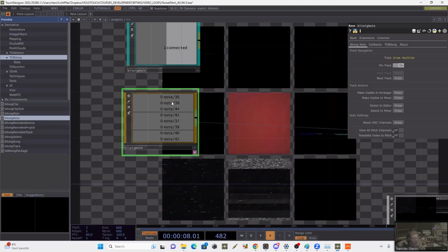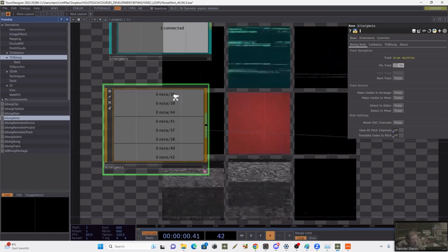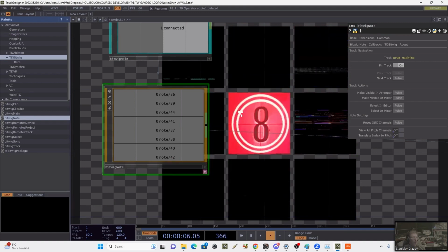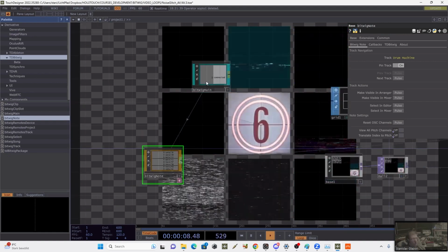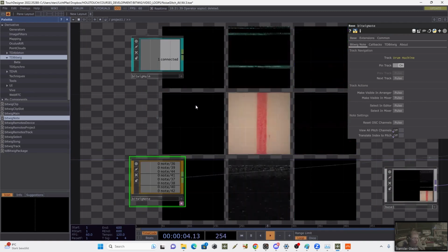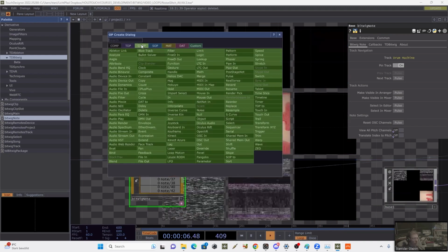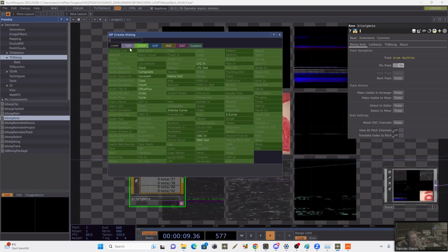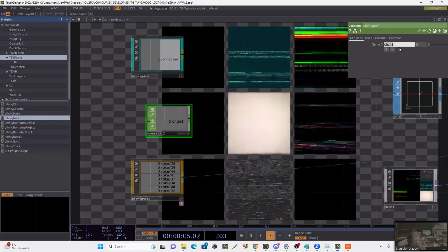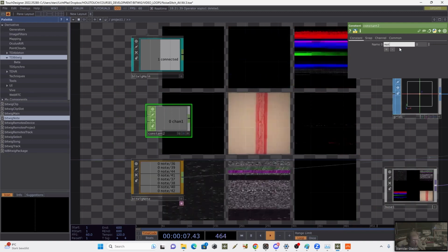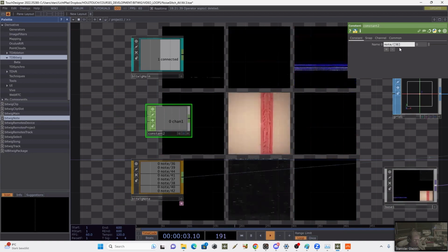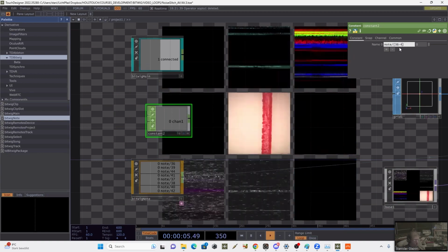So now we can see that we have the notes starting from 36 and going until 42. In order to bring our notes in proper order, I would prefer to generate first the channels and then to control them by replace CHOP. So for that I will create a constant and I will generate the note channels by the pattern matching node, slash square parenthesis 36 until 42.